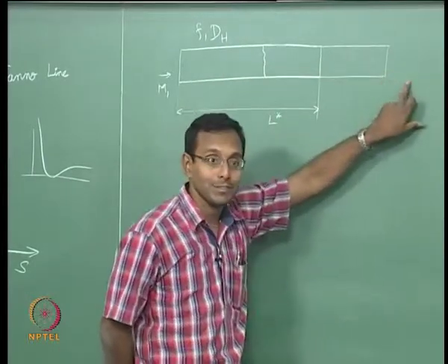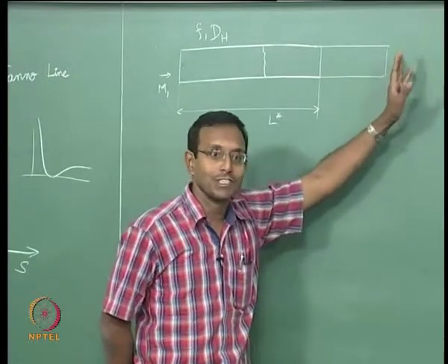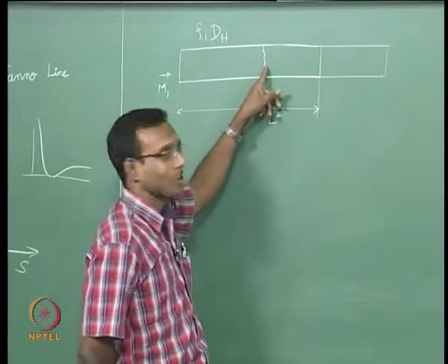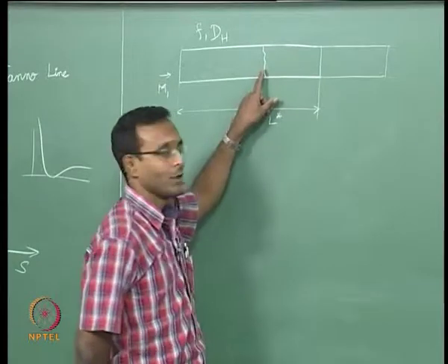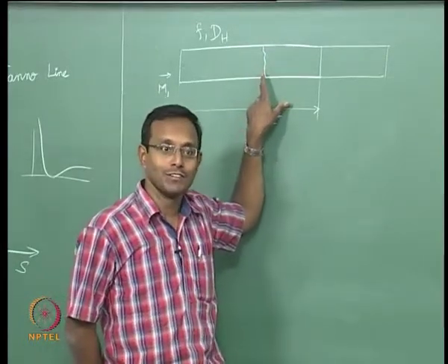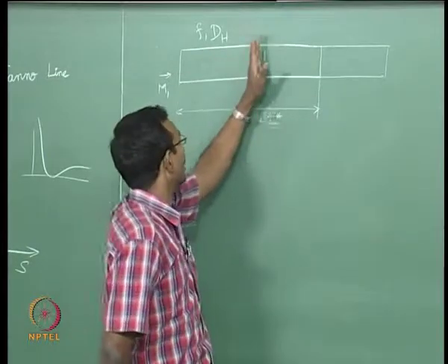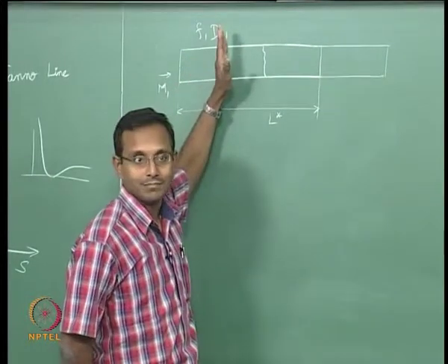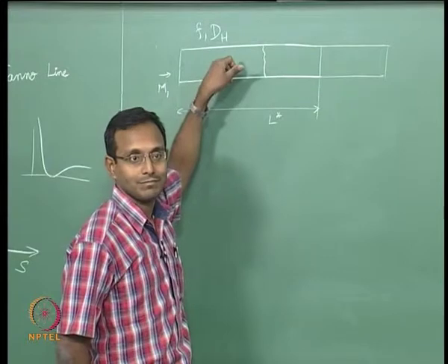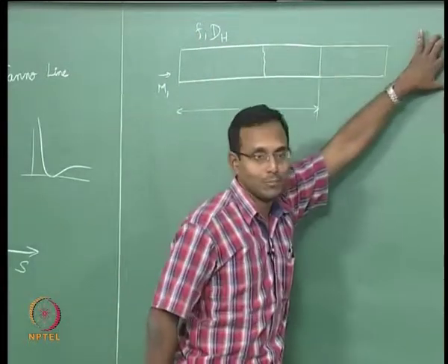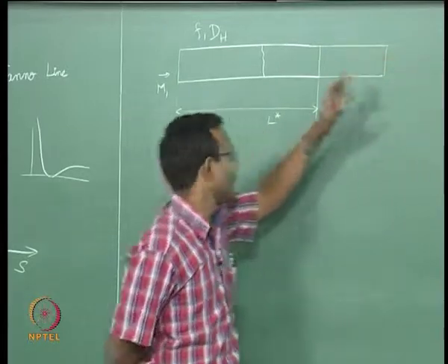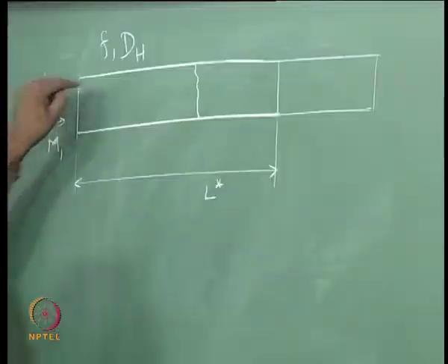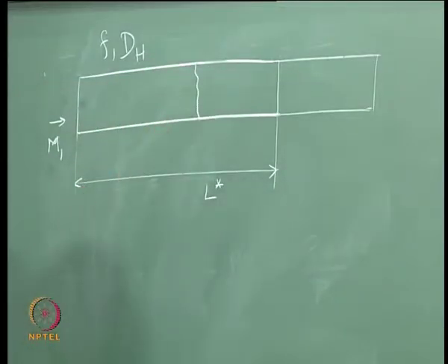If I increase the length further, what happens? One more compression or set of compression waves that travel inward, because it is again retarding. Now it is going to go all the way up to here, because it is all subsonic flow. It will come and reach this point. Now the set of compression waves is much more strong, so they can run against this flow a little more. You go and stand where again the new Mach number of the shock will match the incoming flow and it will stay there. Okay. Shock would have run a little more ahead. Okay. It will go in if I increase my duct length more, and of course if I keep on increasing the duct length, there will be a point where the shock will go sit outside this, and then I have only a pure subsonic problem inside this duct. That can also happen. Okay.